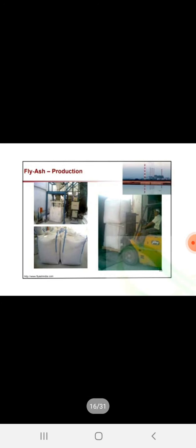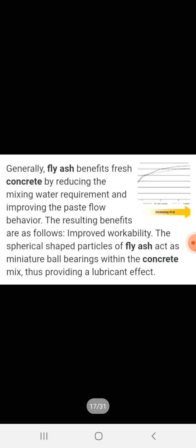These are the pictures of production of fly ash. Generally, fly ash benefits fresh concrete by reducing the mixing water requirement and improving the paste flow behavior. Resulting benefits are as follows: improved workability. The spherical shaped particles of fly ash act as miniature ball bearings within the concrete mix, thus providing a lubricant effect.